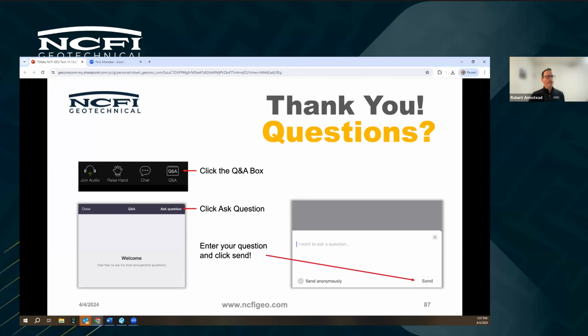All right, next question. What is the best material to use for stabilizing extremely wet soils with very active clays in it? The office space slab that I'm looking at has a lot of constant movement with heaving and settlement. Well, if you've got high moisture content, you definitely want to use one of the hydrophobic systems. If we've got clays, then we're ruling out the single component product lines.